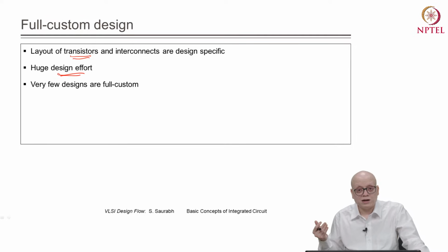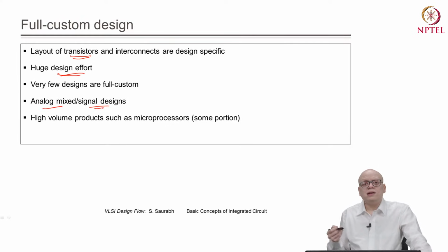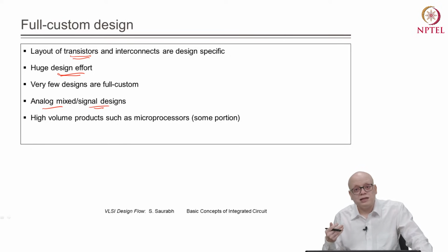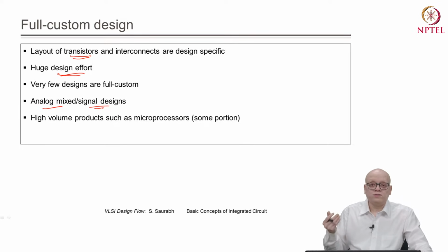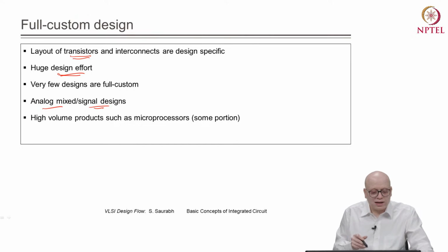are full custom, right? A few examples of full custom designs would be, say, analog circuit design or mixed signal designs, where the design produced by manually designing at the transistor level typically achieves better results or better performance and other measures for analog circuits compared to the automated flow, right?